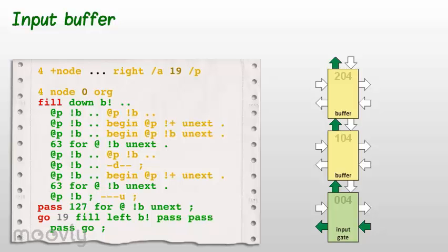204. This is achieved with the following code, which reads words coming from node 5 and sends them downstream. The execution continues, creating a one-word wire from node 104 again and sending jump to down port instruction to node 204. This instructs the node 204 to expect next instructions from its down port. This is from node 304. This way we have switched access to the buffer and data may be read from the buffer by node 304.